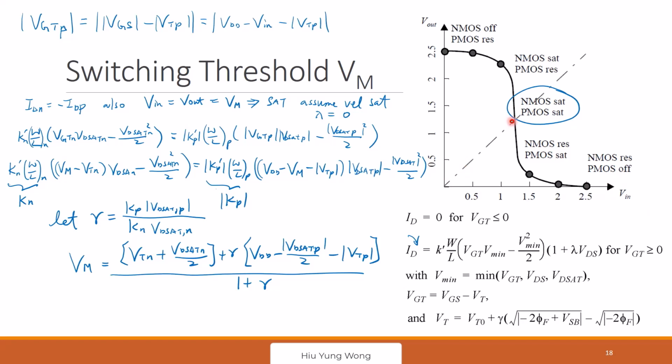Oh, okay, even if they plot more for you, it is still this point. So we don't consider VDD by 2 there. No, not VDD divided by 2. It is when VIN equals VOUT. That's why the definition is very important.